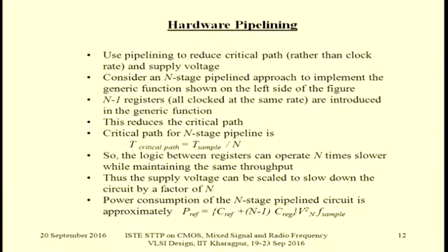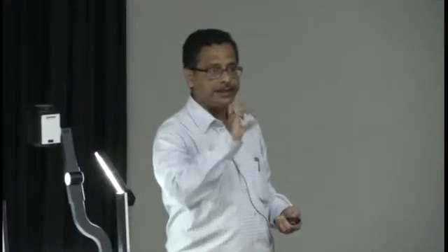Another approach is pipelining. So what is pipelining? Again, this is also case dependent. That means the matrix addition may not be applicable here. But if you think of some application, mostly we have to do, in whatever algorithm we try to implement, say first we do a multiplication operation, followed by an exponentiation operation, followed by, say, a modulus operation. So different computations are involved. Then we can think of a, say, 3-stage pipeline. One stage performs the multiplication, the second stage performs the exponentiation, the third stage performs the modulus operation.